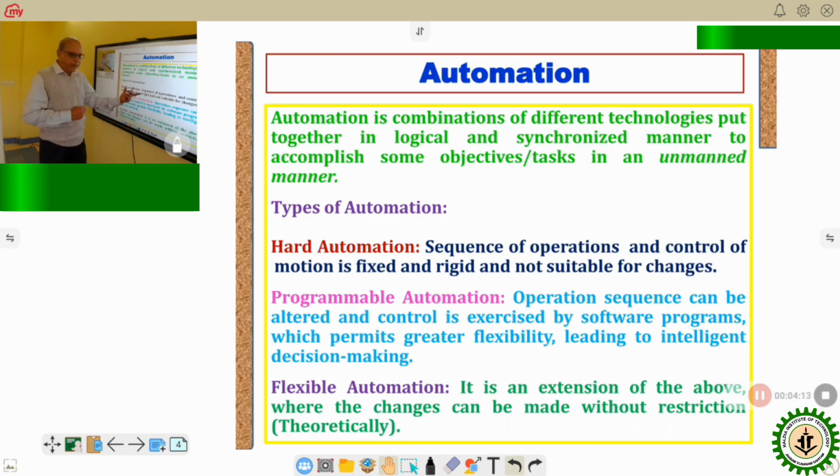For only one particular motion, the performance would be extremely good, but if we want certain changes, the same system will not permit, and that is why it is called rigid and fixed. Whenever flexibility is an important criterion, so that we can switch over from one job to another without marked changes in the hardware, this system will collapse. That is why hard automation was not prevalent in the days of batch manufacturing, and most predominantly with mass customization or mass personalization.